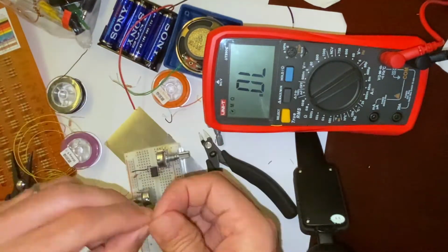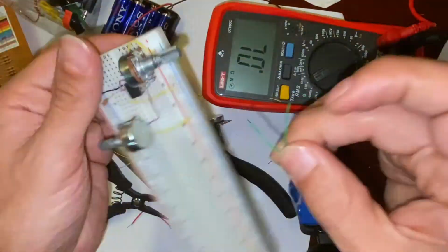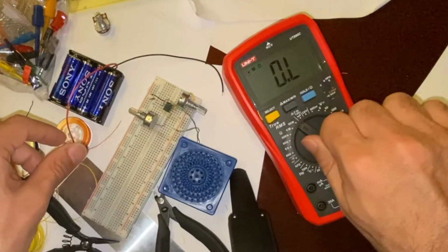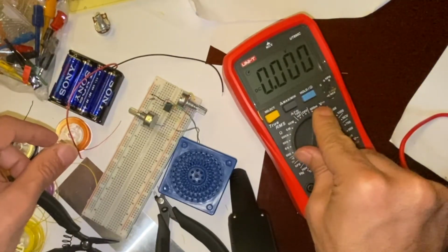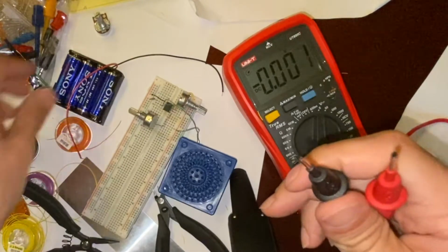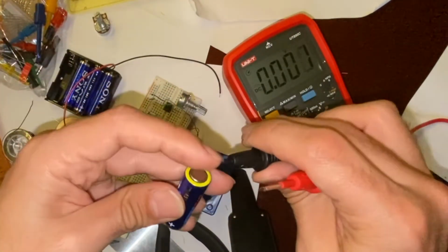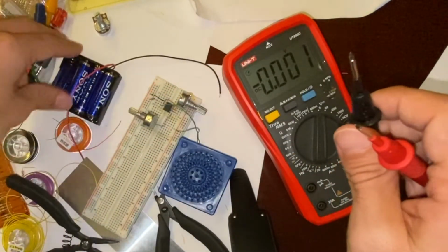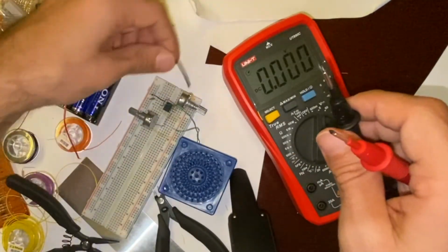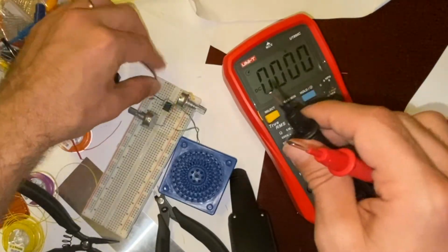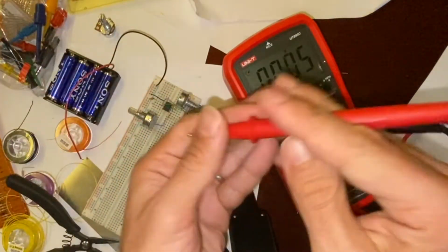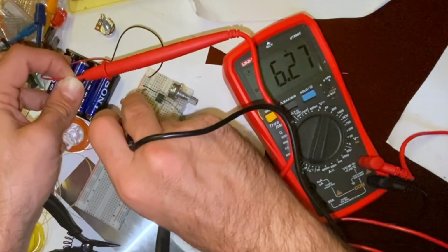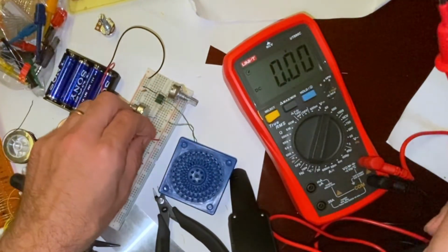You can see that when there are no new components, there's no need to measure them. Then I go with a little bit of careful measurement when I get to put the batteries. I'll double confirm. I put in voltage. The tip: I use 6 volts, and then I see one battery is about 1.55. I connect the black terminal with ground, and now I'll set the instrument higher than 6 volts so it doesn't go over limit, and I measure 4 of them.